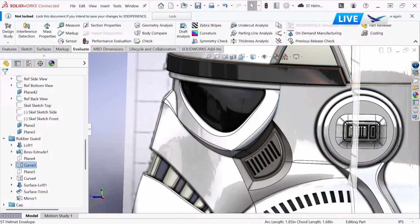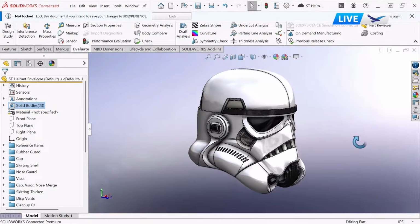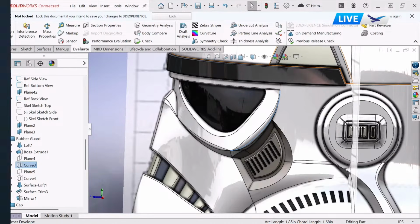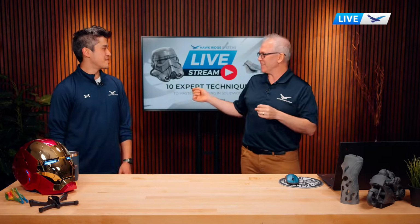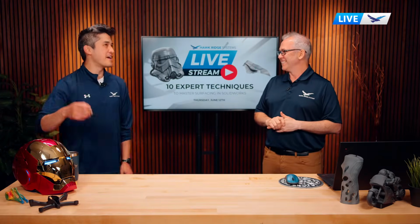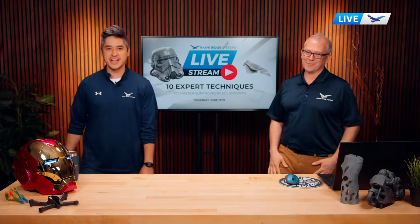And if I'm able to share this model, you'll see this in the model, but I like to take various sketches and create almost like branches inside the sketch, and then the end of that branch is a point on that sketch, and I'll use that to place my 3D sketch. Then when I go back and modify those sketches, it relocates that point, which modifies the 3D sketch. It's very complicated, kind of a beautiful mind way of thinking. Or you can do projected curves. Or projected curves, yes. I like it.